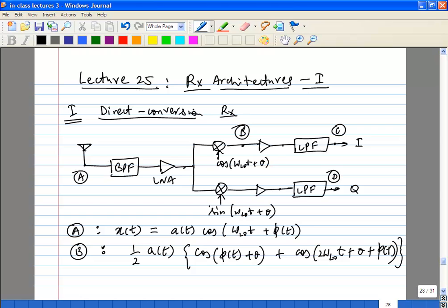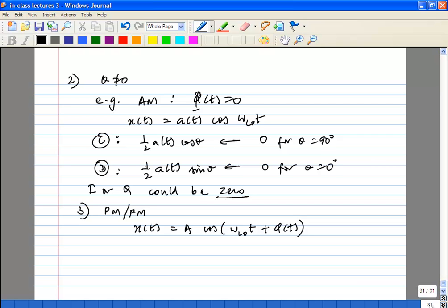By zero crossing or something like it. No, because that will be extremely difficult, calculating it just based on zero crossing. Because if it is a pure sinusoid, you can do it based on zero crossing. But in general, if it's a modulated signal, you can never do it based on zero crossing. That's for sure.